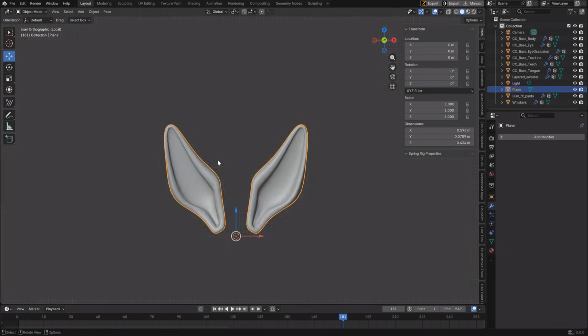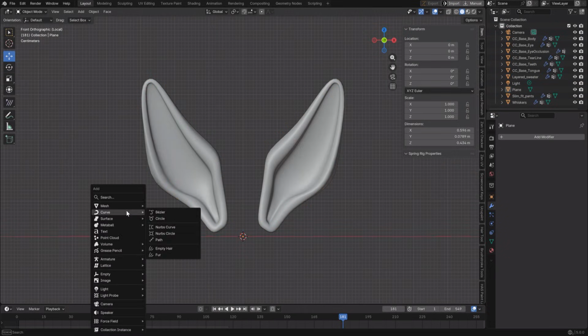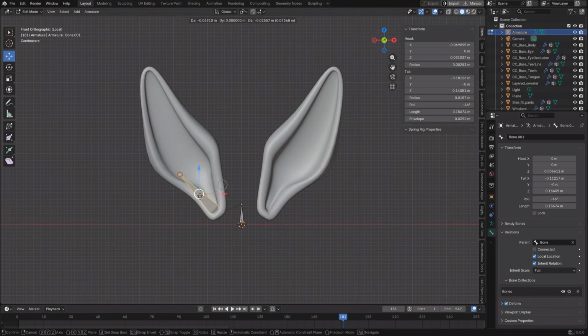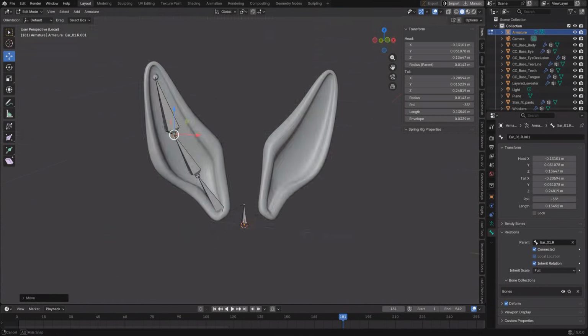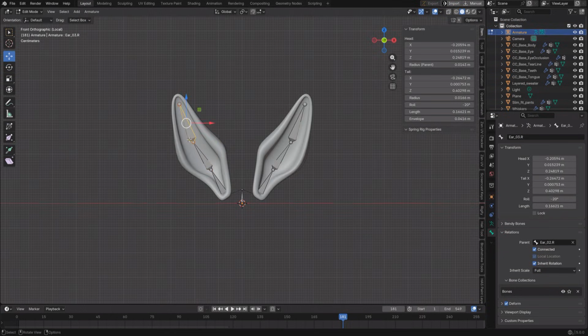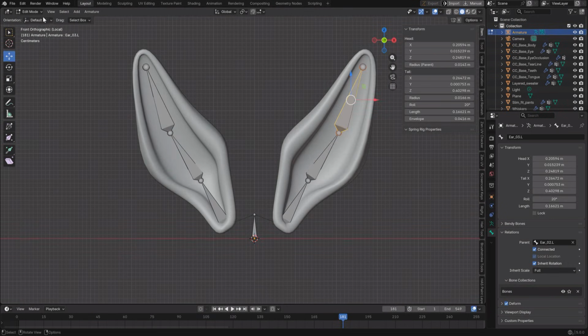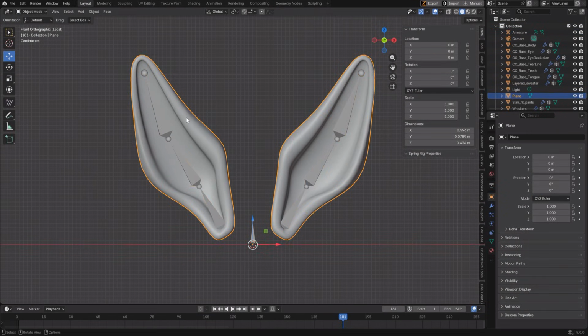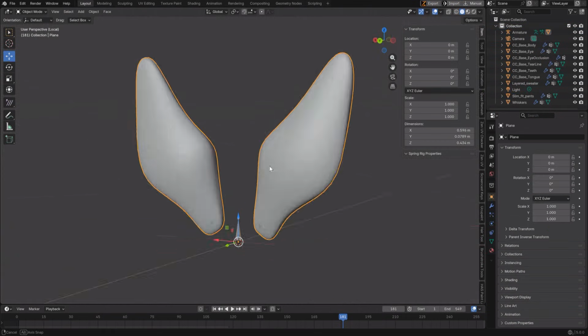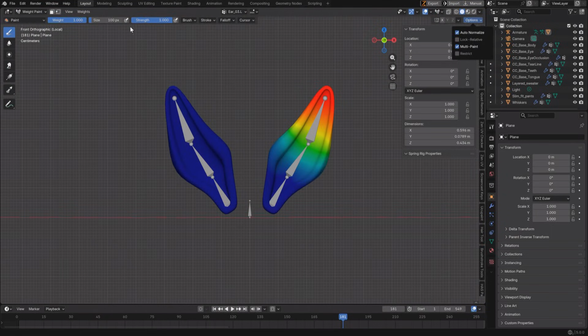Now, when I rig an item, like these ears, which are going to have spring bones, I always pull everything down to the center of the scene, because I don't want the bones to be kind of floating off into the air from a different origin. I've had problems with that before. So I pull the ears down to almost 0, and then start the rig there. Whether that's the correct way to set up a spring bone accessory or prop that attaches to the head, I don't know. It just makes sense to me to do it this way.